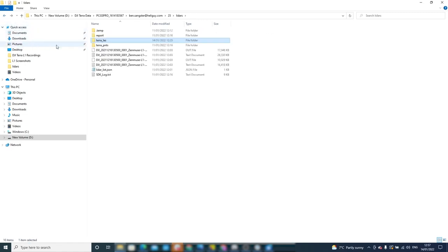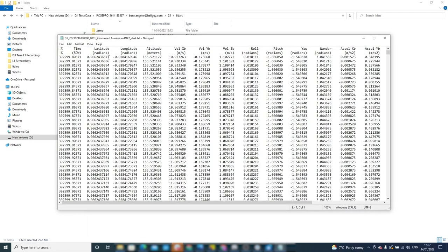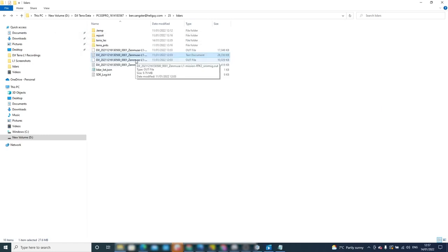The second file is the SPET file, also known as the post-process trajectory file for the mission. This file contains trajectory information for the process solution. As per the LAS file, this can also be exported to third-party software and does not require a second adjustment if the Optimize Point Cloud Accuracy function was enabled. Encoded within this binary format is information regarding a GPS time, geodetic coordinates, altitude, XYZ velocity, XYZ acceleration, XYZ angular rate, as well as roll, pitch and platform heading.